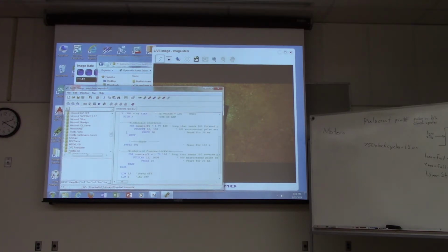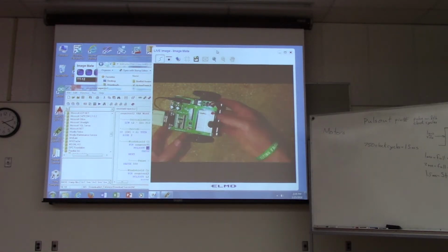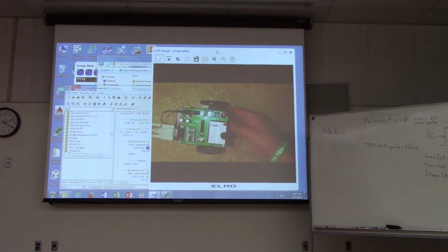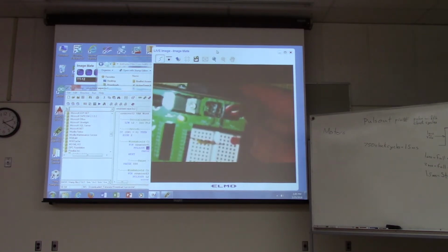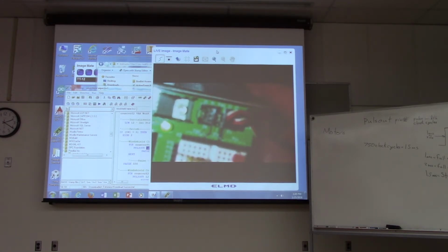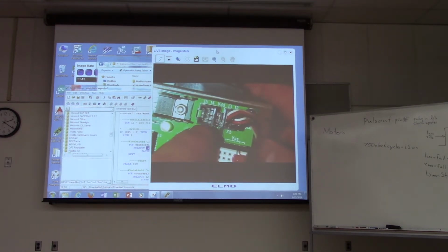and it looks like I've got my servo motors plugged into the wrong place. Okay, so without going into too much detail on the code, we can see that we're looking at pulse out on 12. So that means that we're sending commands over on pin 12. Up on the top of the board is where you can attach your servo motors. There are these little sockets that have positions for servo motors.